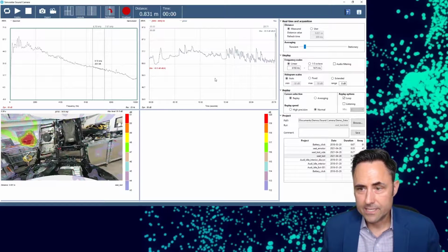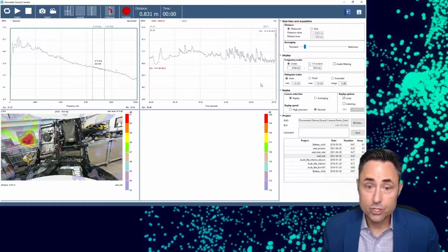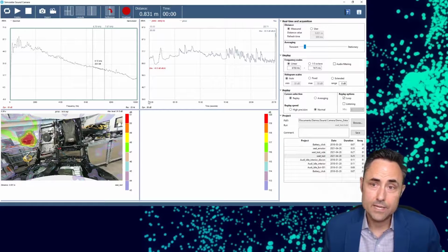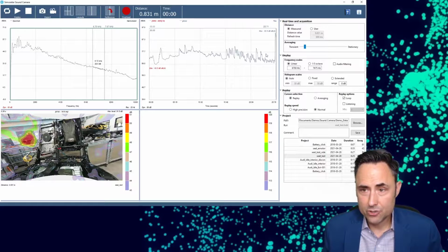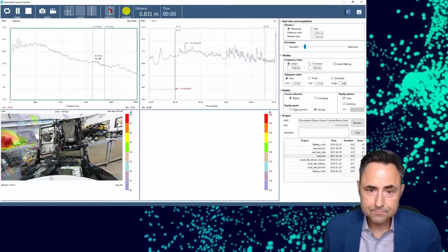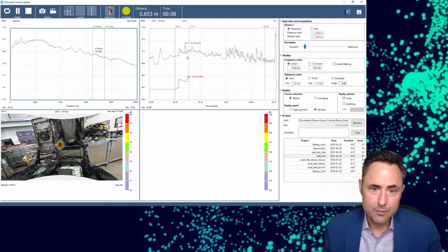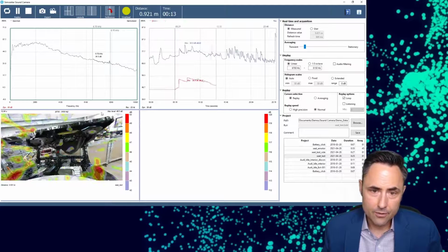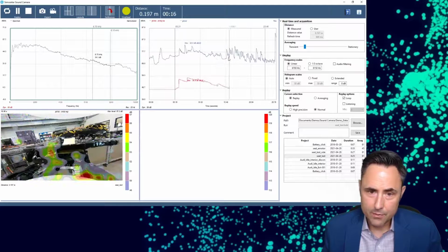One of the nice things about the sound camera is that I can do motion or transient noises. In this case, we have a seat mechanism that had a noisy mechanism, and we want to figure out exactly where in the mechanism it is. You can see the time history over here, and these transient clicking events. I can take these X cursors in my time domain and hit play, and as I go through the time domain, I'm localizing these frequencies and I can tell where the noisy part of the mechanism is.